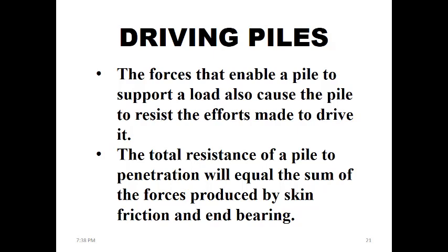So the total resistance of a pile for penetration will be equal to the sum of the forces produced by the skin friction, the surface area, and the end bearing, the tip of the pile itself. So these load-bearing piles, as I mentioned in the beginning, work with two fronts: the tip and the skin friction.